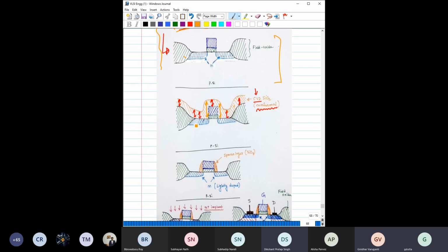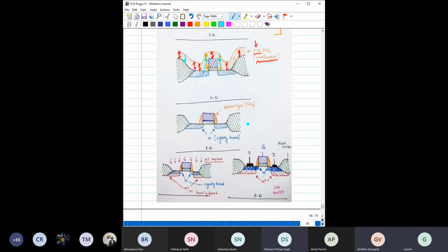Then you etch the silicon dioxide exactly by this amount. You have different dry etching techniques, so use those to etch this oxide layer by this amount. Here you etch this amount, here also this amount. So after this etching, you will be left with this much of oxide.